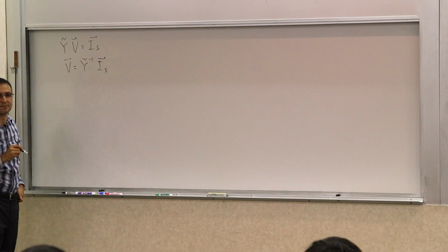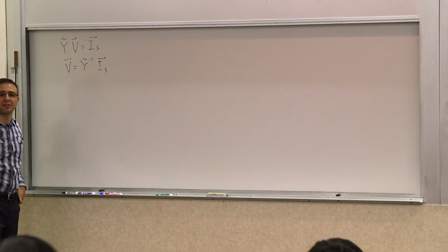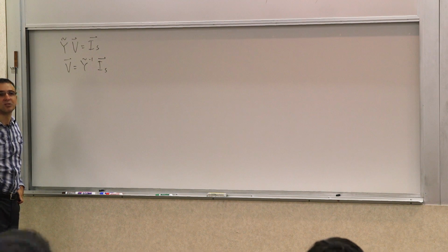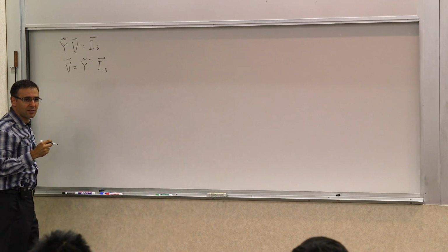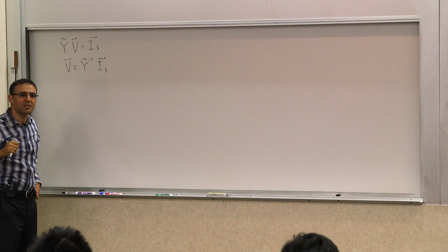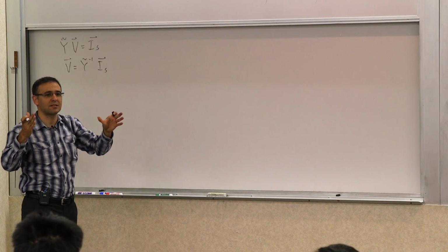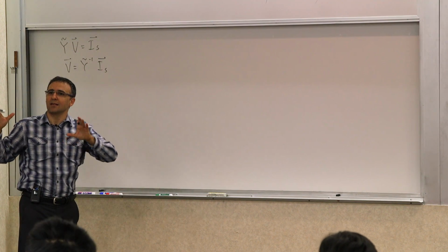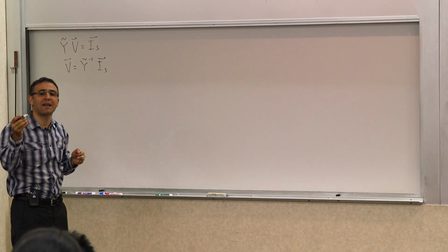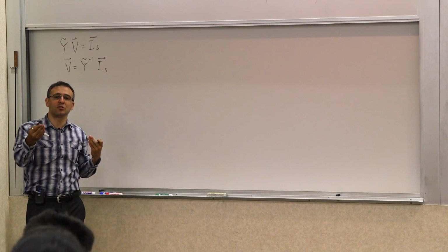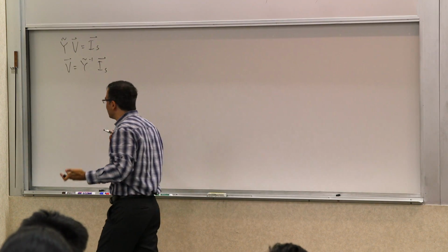Yes? When Y is non-singular. When Y is non-singular, when you can invert it, which basically means another way is, what can you say about it in terms of its determinant? Determinant is non-zero, right? So if you have a determinant that's non-zero, you can basically invert it. So the question is, this is a mathematical thing. Can we translate it to a circuit characteristic, something that we can look at a circuit and say, this circuit does have a solution or this circuit does not have a solution? Can we convert this? And this is where the Y matrix analysis formation comes into use, because you can actually think about these inverses as entities and play with them and come up with results.